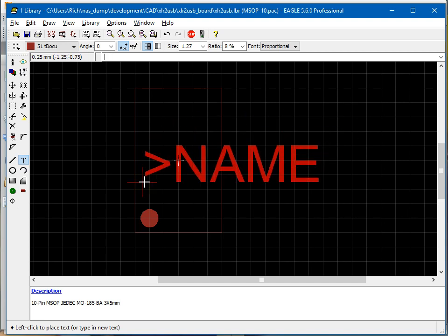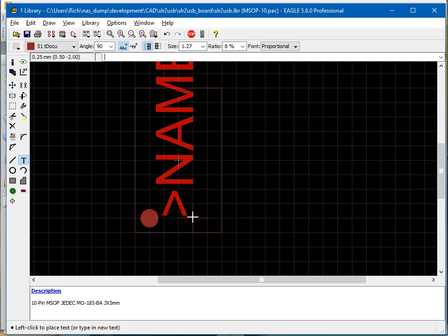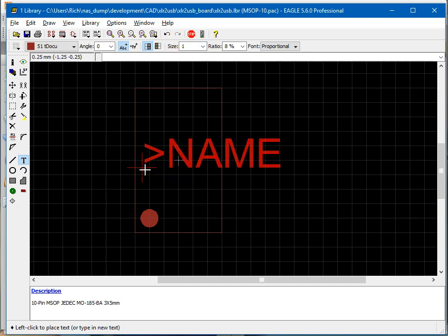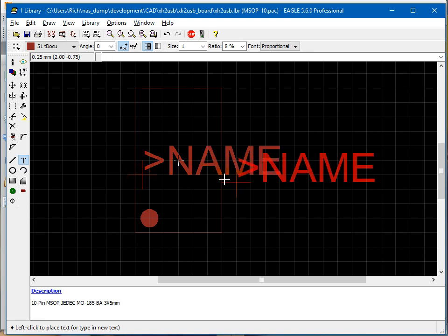Now you notice this is a little bit fat, right? If I get into reference designators like U13, that's 3 digits, even though the 1 is kind of narrower than the U and the 3, but that's still too fat. I could turn it, right-clicking here, I could turn it sideways if I wanted to. That would probably be the easiest way. Or I could just change down the size a little bit. So I'm just going to make it, I don't know, 1 millimeter tall. Will that fit? It gets me 3 digits, and I'm not really envisioning having more than 100 parts in any section, like the U's for reference designators. Maybe on a more complicated design I might have that problem, but for this one I'm good. Okay, so click it there, and I'm done.